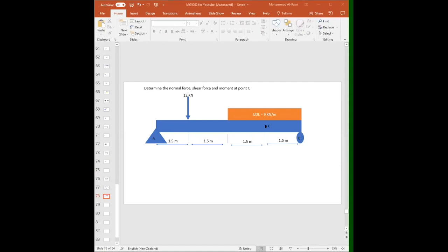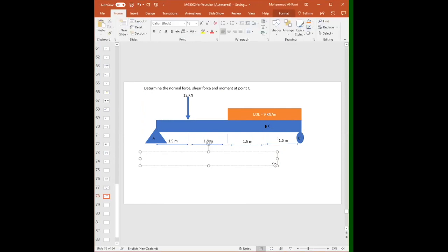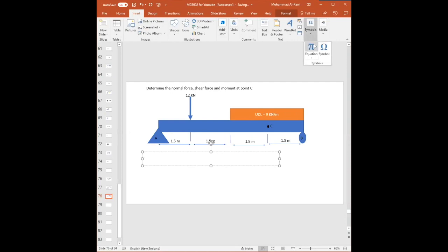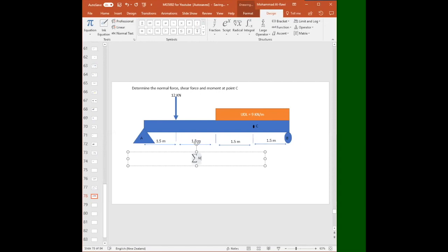All right. Now, how can we solve this question? First of all, as we say, we start with the free body diagram. I will help you, it will be easier. The first thing I will start is to take a moment around the point I prefer. Let's say I will take the moment around point A. So insert equation: algebraic summation of moments about A is equal to 0.